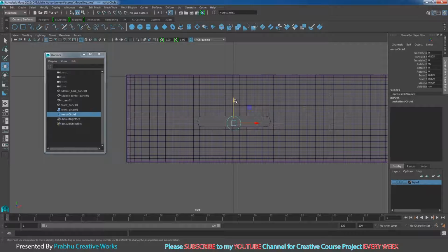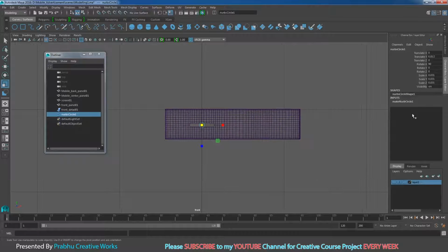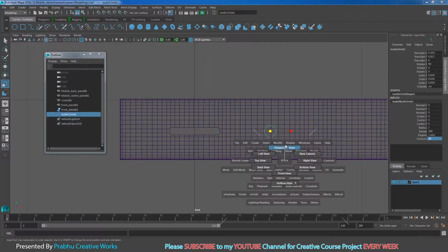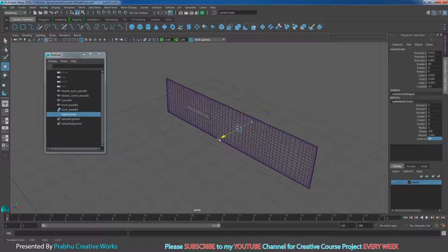So press W, I want to move a little bit over here, so I will scale a little bit bigger. So this is the camera part. So go to node circle 1 and set section divisions to 20 and press W. I want to move this one to this side. Press R and scale a little bit bigger. I want it a little bit bigger than this hole. So go to perspective, press W. You want to move this in Z.